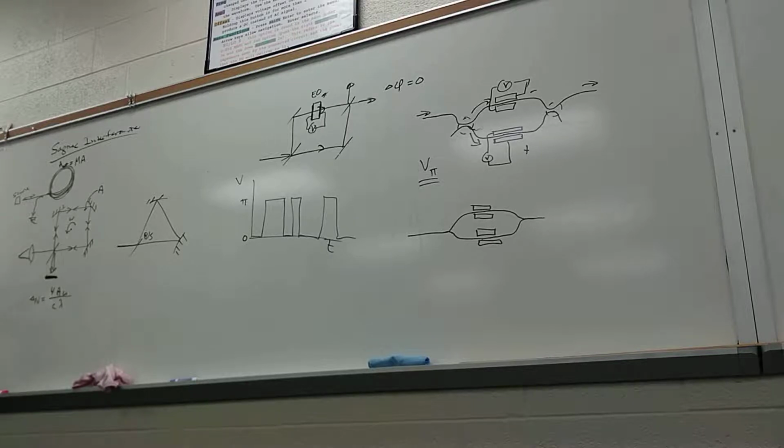For any of these gyroscope approaches, the name of the game always comes down to angular drift: how many degrees per second or per minute or per hour is the drift in your measurement, meaning it looks like there's a rotation, but there really isn't. That gets back to a bunch of noise properties, and what you want is a really, really low angular drift. I used to know the numbers off the top of my head, but I don't remember them anymore. But for an airliner and the really expensive laser gyroscope that goes inside of it, it's fractions of a degree per hour. It's really small.